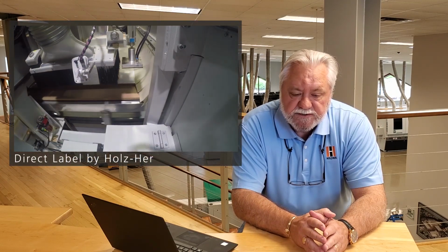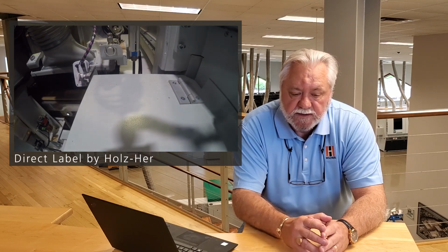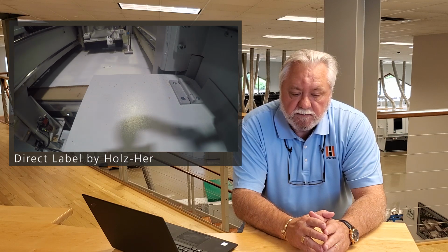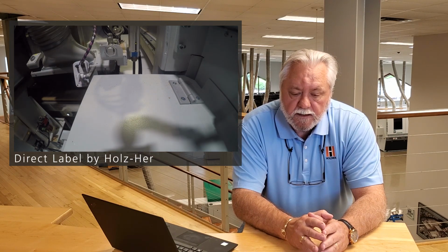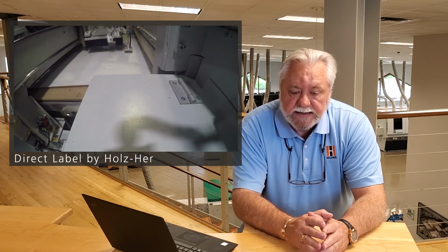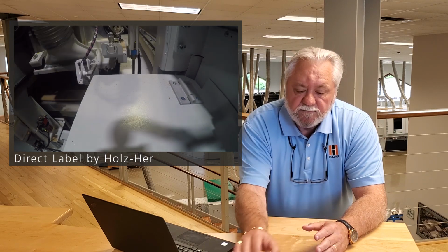Direct Label. Direct Label provides for an automated labeling of the sheet prior to the machining operation while the panel is clean and dust-free. The applicator is mounted on the machine gantry arm and the printer unit in the gantry support arm. The applicator has a 90-degree rotation, and again, the labeling software is analyzing the tool path and the drill routine from the HOPS software.